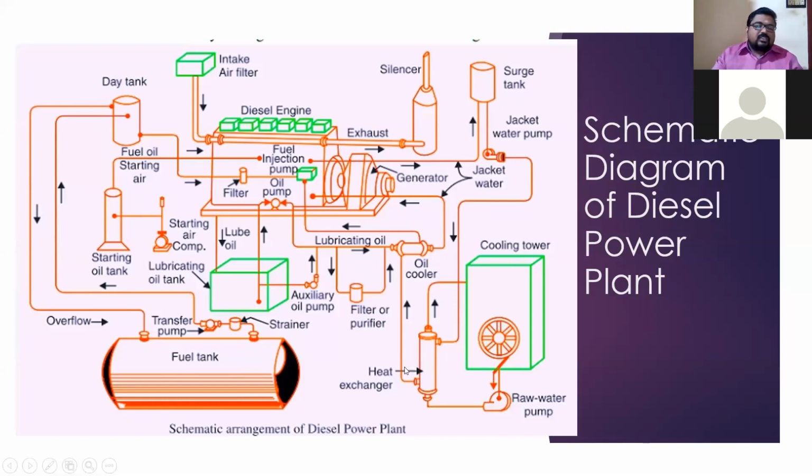Why it is a heat exchanger: if it is direct water, then we can mix it or take it directly to the cooling tower. If it is a coolant, we can't mix it with normal water. So a heat exchanger is provided. Inside the heat exchanger, it is similar to your thermal power plant. I told you, in a superheater or in an economizer, everywhere one pipe, this coolant will be going, and outside of that normal water will be there. So that is nothing but similar to a condenser.